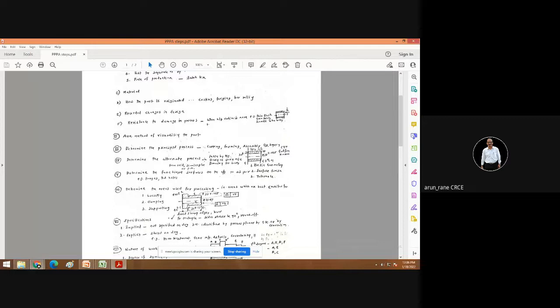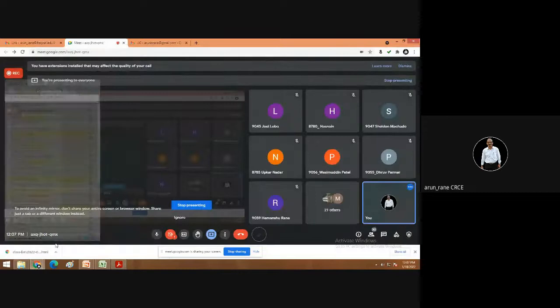For example, suppose a gear, a 40 teeth gear. What will be the different processes in this? The basic process will be forging, that is, the blank or the raw material is in forged condition. Then you will do raw material inspection. Then you will turn the blank. In turning, you will turn the OD, you will turn the ID, that is bore the ID, and facing. Then obviously it will have some keyway, so you will do it on slotting. And then teeth cutting, that is 40 teeth cutting. And then final inspection followed by packing and dispatch.